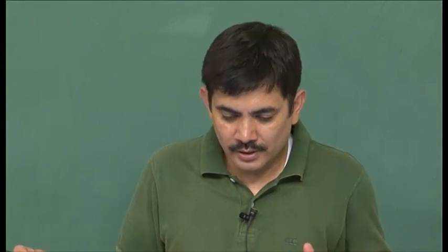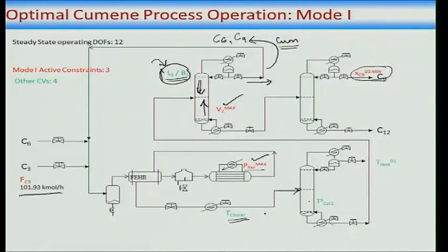Okay. Now what else? Let us go further. So we have got the feed fixed, 1, and 3 active constraints, that is 1 plus 3 is 4. These 4 things I have just explained, that makes it 8, and what that leaves are 4 unconstrained degrees of freedom, which are economically quite important, and I will tell you why they are economically important, and these are put here.